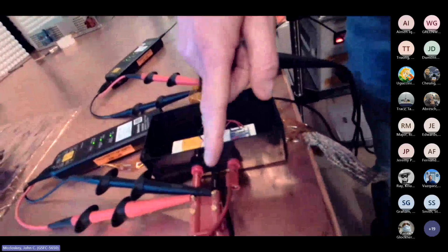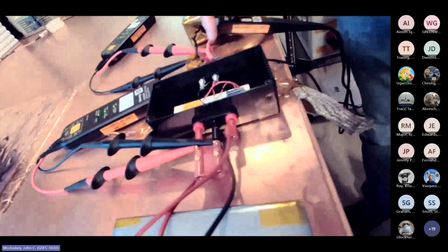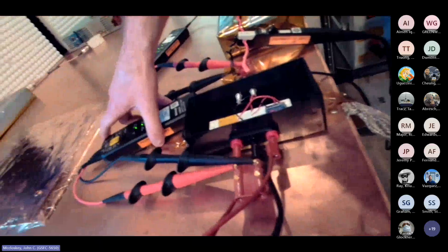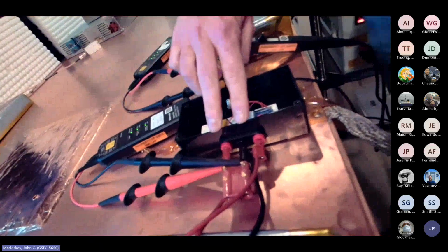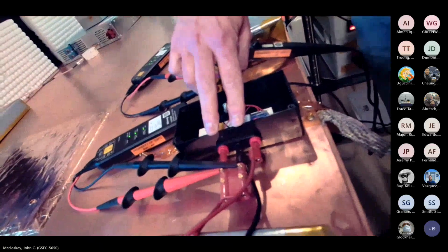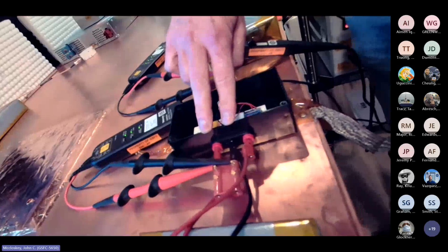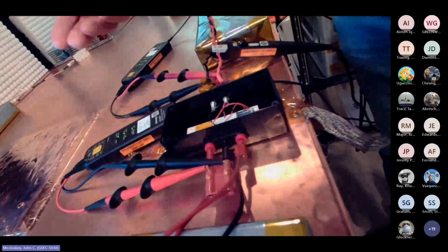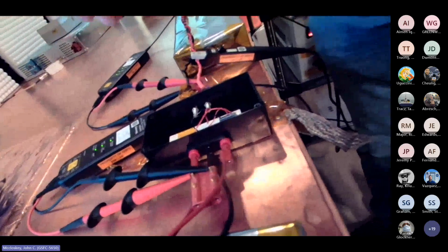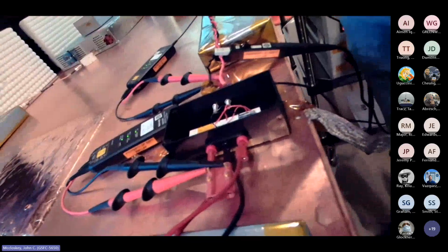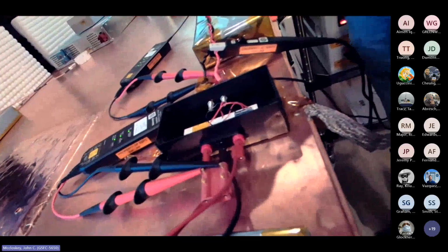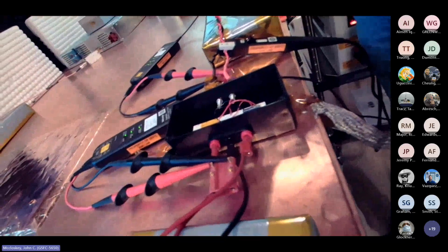It's just the output level, right? So I've got another differential probe here across the plus 15 volt output, and we're just going to look at ripple on it. Now it's probably a bit more complex than that, but for this demonstration, I'm just going to be looking at the ripple of the plus 15 volt output on the scope.